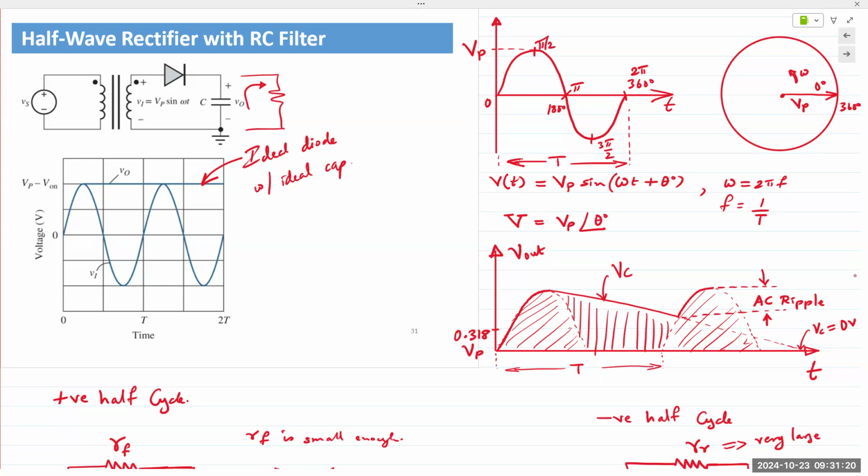And students who did the lab yesterday, we used the electrolytic capacitor. You saw how small the ripple was when you used it. If you have the lab tomorrow, then we can test it out right there. We have two capacitors in our lab kits. With the smaller capacitor, you'll still have a larger ripple voltage, but with the bigger capacitor, the ripple voltage is in millivolts. Very, very small. Okay.